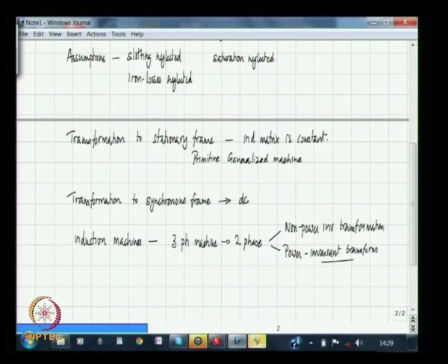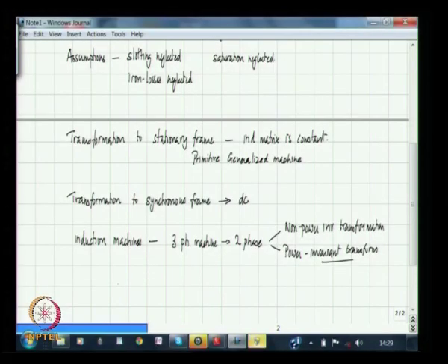So this provides the link between the three-phase and the two-phase machine, and we saw how the machine description was derived, going from the basic ideas of a single coil winding, a distributed winding and so on, all the way up to the set of machine equations that we have. We had made no reference to the equivalent circuit which one studies in the first course on induction machines, and therefore we tried to establish the relationship between the equivalent circuit and the equations that we have derived, and we found that these two agree with each other.